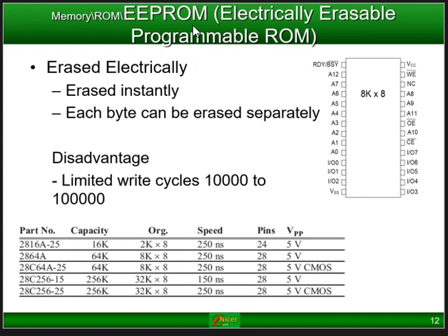On the 8051, there is also a common way to make use of an external EEPROM where you store your program, which can then be read from the EEPROM. It's electrically erased, as I've said. You need a programmer for that, in other words. It is erased instantly. In this specific device, you will be able to erase certain registers or locations. As it says there, each byte can be erased separately.